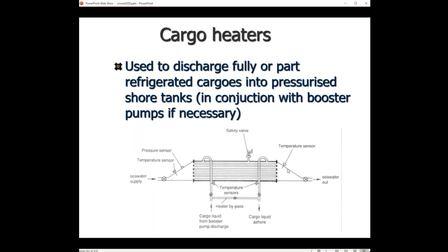If ever you fall asleep and this temperature achieves +5 degrees Celsius, your cargo pump and your booster pump are stopped automatically. Not the seawater pump, of course. The seawater pump is kept running just to add some additional heat and to warm up the cargo remaining in the heater. So this is an automatic protection of your heater.